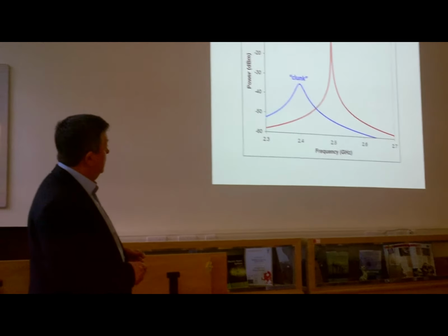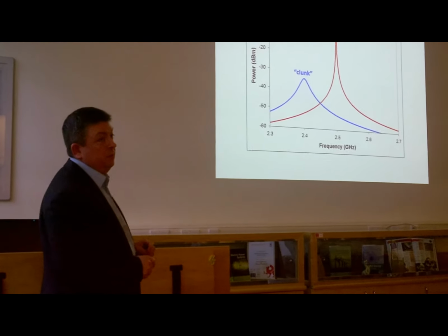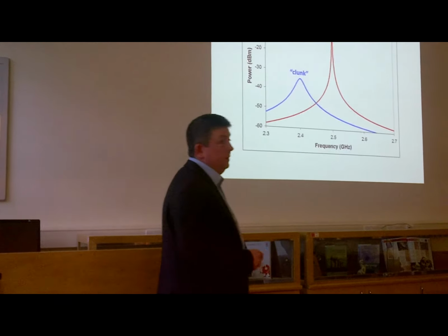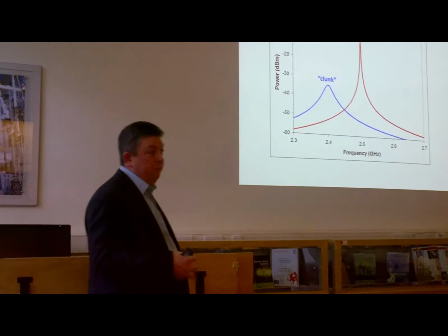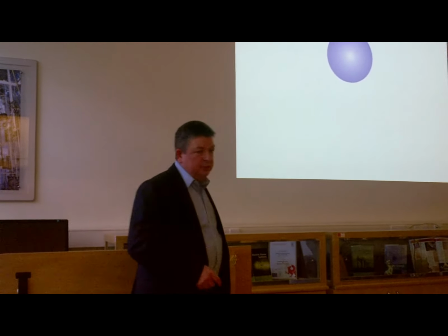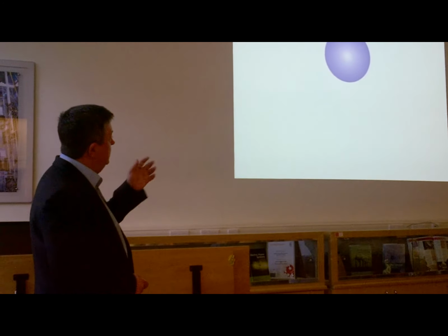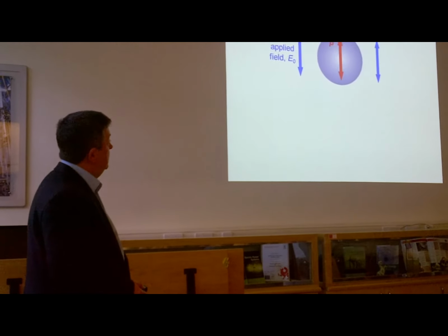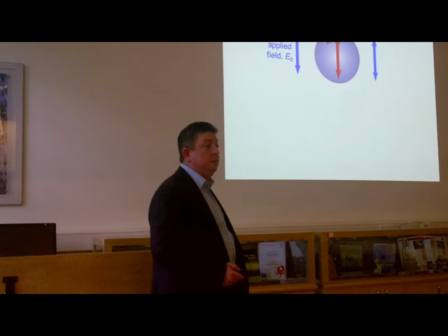So what we're interested in doing, not acoustically, but using microwaves, is to look at, first of all, the shifting resonant frequency, because that tells us about the redistribution of energy in the cavity. And then we're also interested in measuring the change in the Q factor, or equivalently the change in the resonant bandwidth, or the 3 dB bandwidth. That's linked to the power level as well, so that's not an independent piece of information. So that's what we measure. It's the change in frequency and the change in Q as a result of interacting the fields with a particular sample.